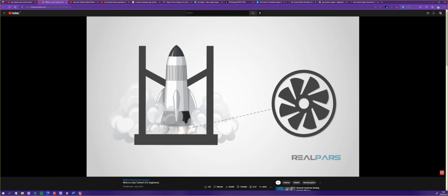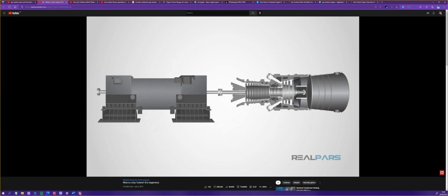In that, we've transformed the chemical energy of fuel gas into rotational mechanical energy of the turbine shaft. Now, I have a prime mover for my generator in the above power plant example. Also, this prime mover concept can be used in different applications like turbo compressors or the like.